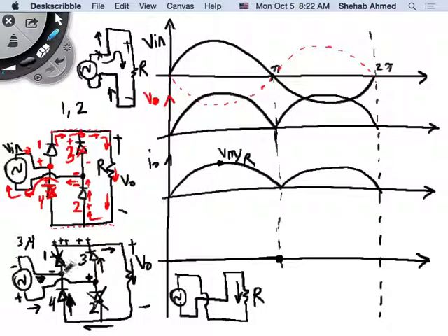At one side, it has this supply terminal, right? And then 3 is on. So on the other side, it sees the other supply terminal, right? So it's seeing the voltage at the input across it, right? Do you see that or not? Because 3 is on, the other supply terminal is now across diode 1, right?